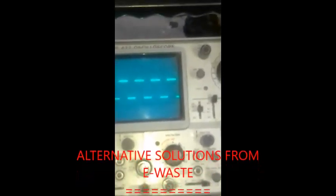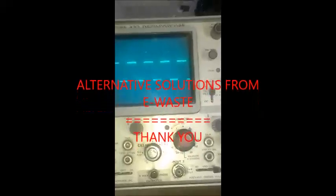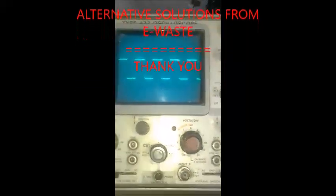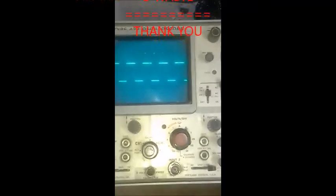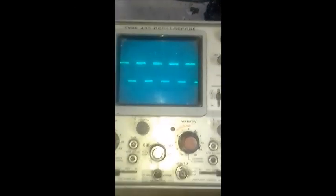So a MOSFET can be used as a capacitor. Of course, bear in mind that the maximum voltage is 20 volts, because the gate-to-source voltage maximum is 20 volts. It has no polarity, you can put it either way. So that's our MOSFET as a capacitor. Thank you.